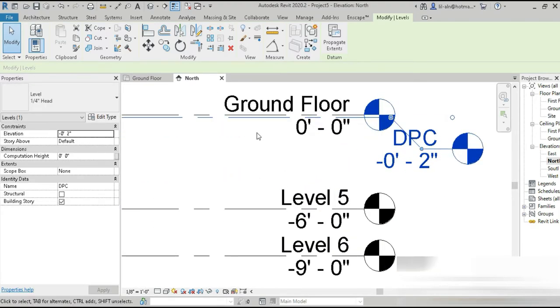Now, as far as this distance is concerned, this is the thickness of our load-bearing wall foundation, our stepped foundation that we made in our last videos. If you guys remember, the first layer was 1 feet and 6, followed by 3 more layers of 6 inches, and then 12 inches, and finally 1 feet of PCC.